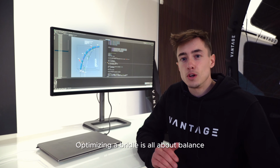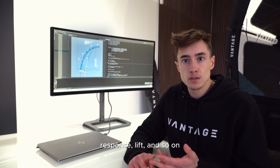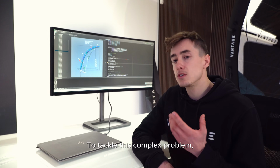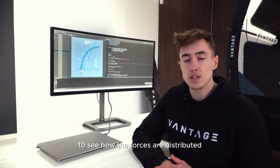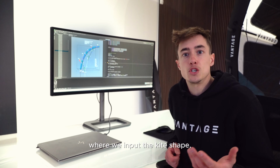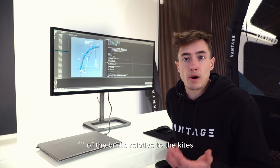Optimizing a bridle is all about balance. Balancing the steering pressure, bar pressure, stability, response, lift, etc. There is no single perfect answer, it's all about the best trade-off. And to tackle this complex problem, we simulate the bridle in a computer to have a better understanding of how the forces are distributed. And here, for example, you can see the Python codes, and we put in the shape of the kite, the bridle configuration, the lengths of the lines, and the angle of attack the bridle has relative